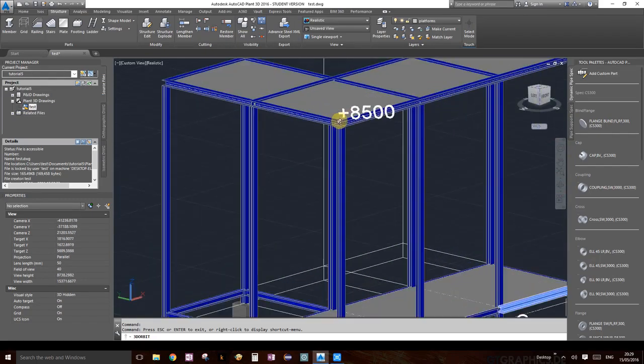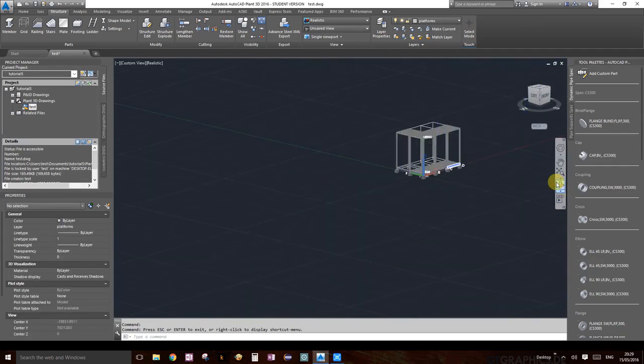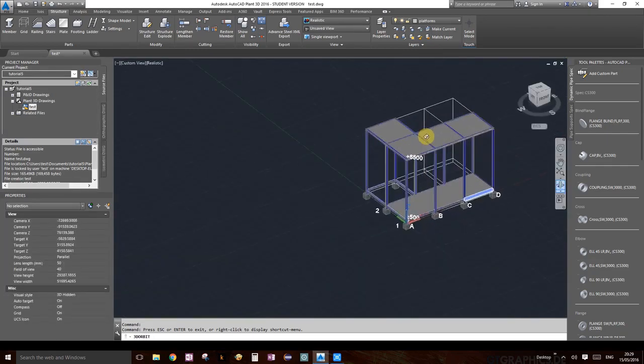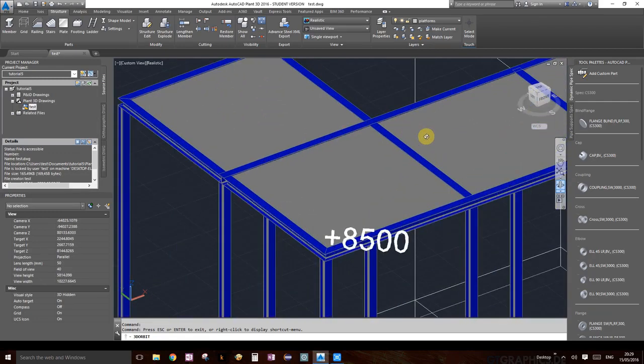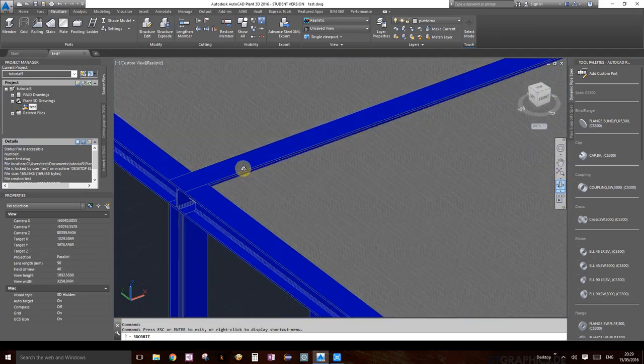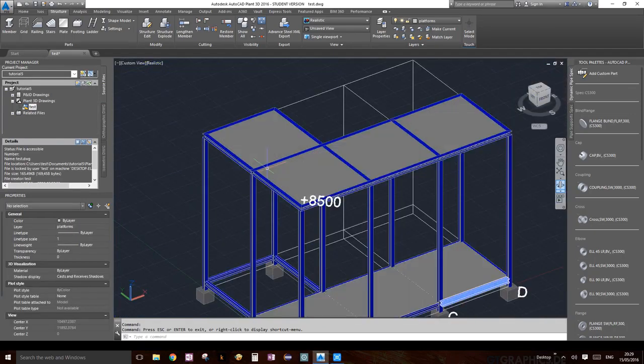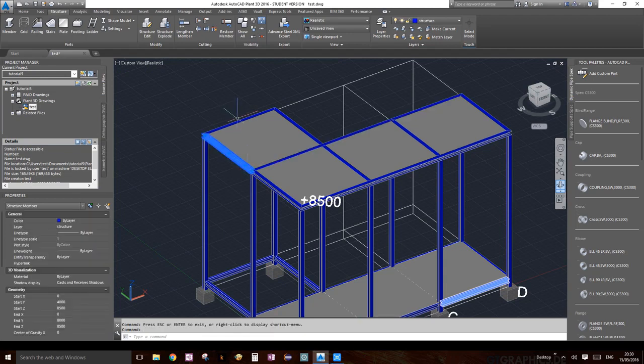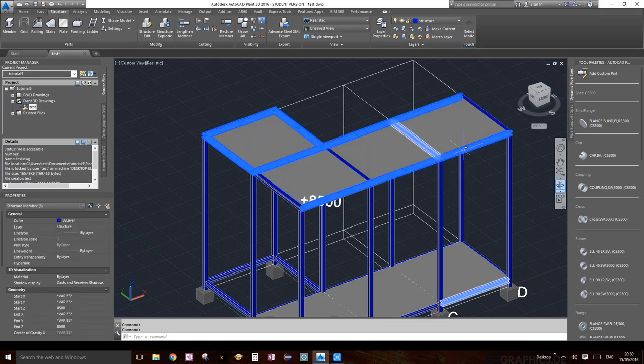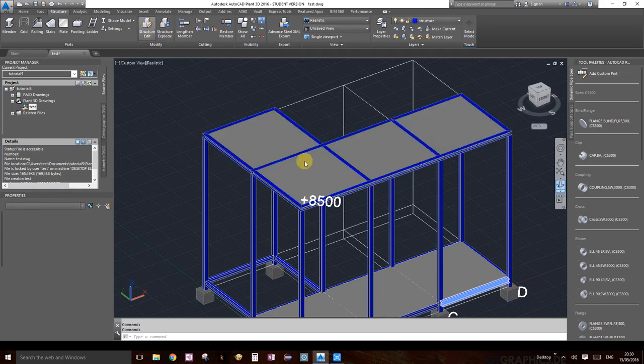And one thing I did notice though, that if you were to move it up, for some reason our structural elements actually show up, and that's pretty bad. I know why. Because we are actually supposed to change the reference point of the structural members to the top. We didn't do it, so it's actually snapping onto the middle of it, so that's not good. Let's go ahead and change that.